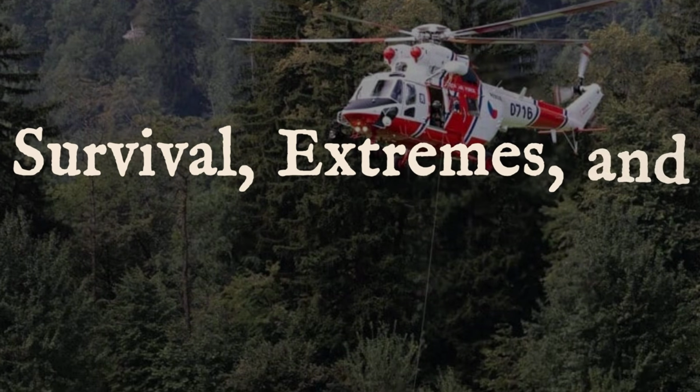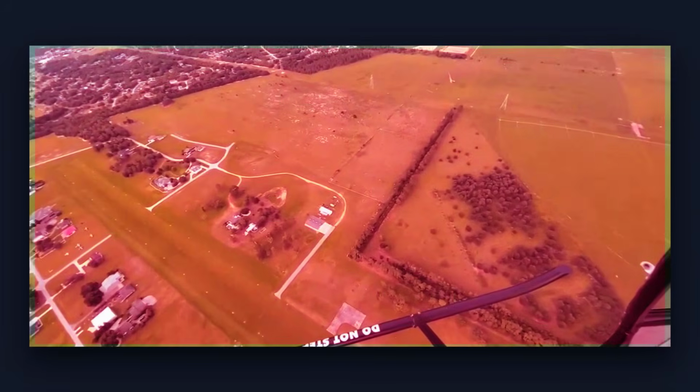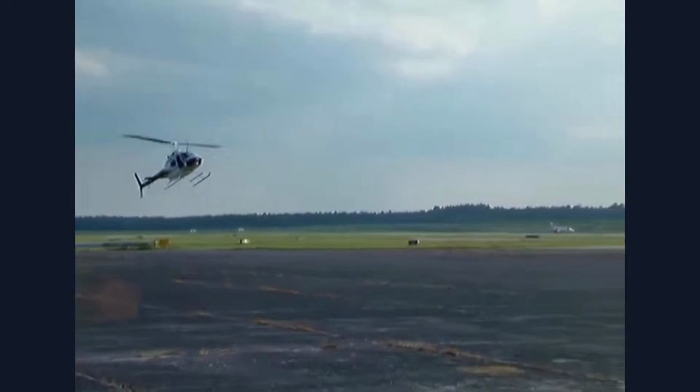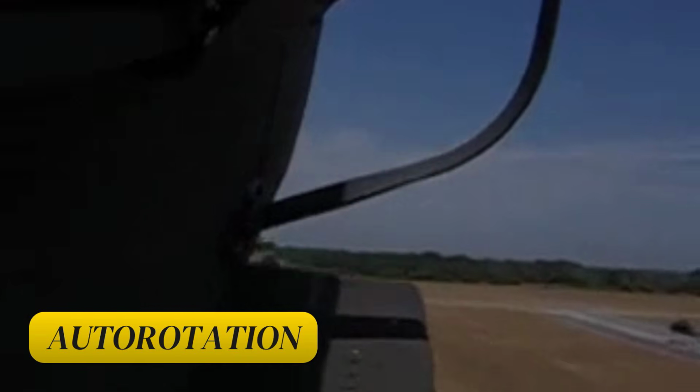Engine failure in a helicopter is not a death sentence. The moment the engine quits, a freewheeling clutch silently disengages, letting the main rotor spin untethered, driven now by air rushing up through the blades as the aircraft descends. This is autorotation, a physics trick every pilot trains for.